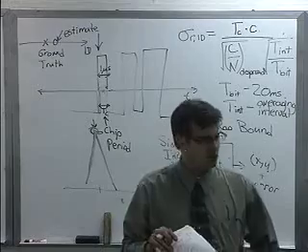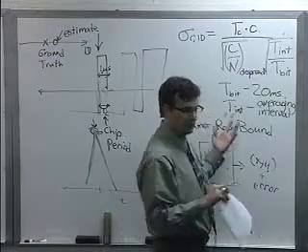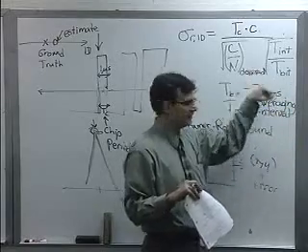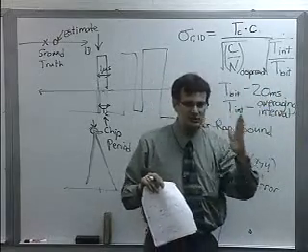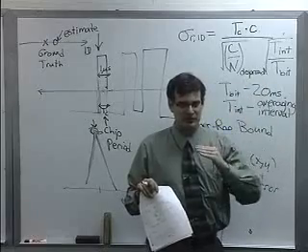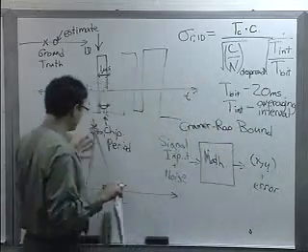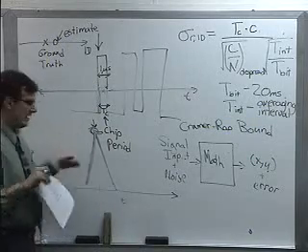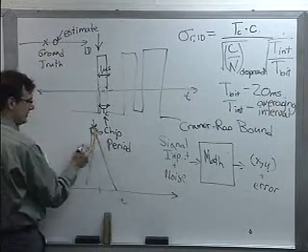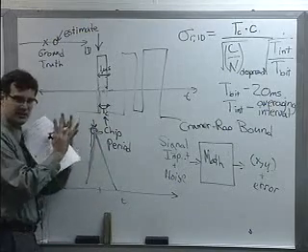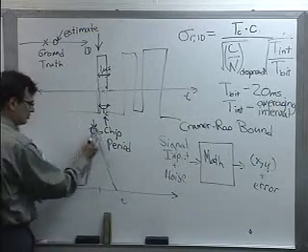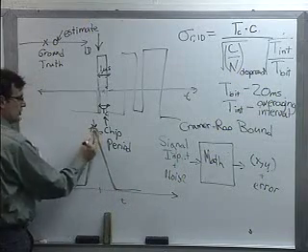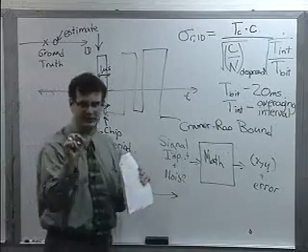But if you do 20 bits or 100 bits, this is how a lot of GPS receivers crank up their accuracy. They'll just sit there and integrate on each bit, on each satellite spread spectrum stream coming in. And it's effectively like averaging. They'll calculate a correlation period, and then another one, and another one. And each one will have a little bit of noise added to it. But if you average a whole bunch of them together, this underlying triangular structure is still there. But the noise should average out, and you should get a really clean correlation peak.